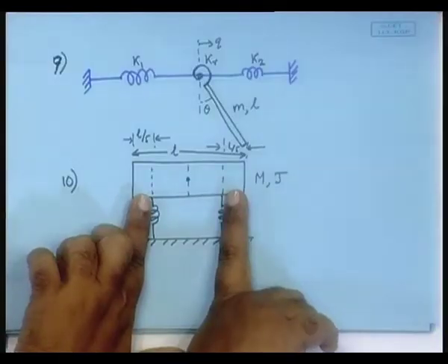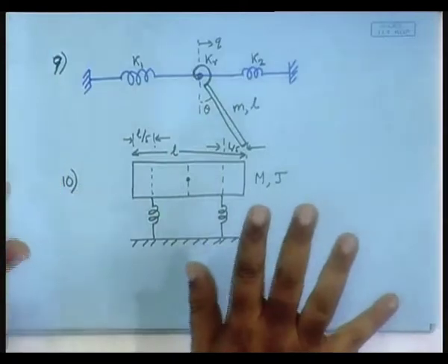So, what are the degrees of freedom and how is it allowed to move? Just one mass, remember, but the same mass will now have 2 degrees of freedom. It can go up and down, it can also rock like this. Okay. So, in order to define the positional status of this system uniquely, how many variables do you need? 2, one representing this position and one representing that, and the elongation of the springs will have to be measured from both.